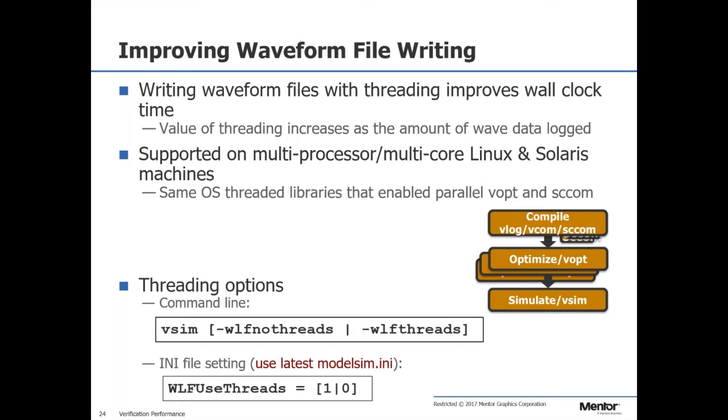So if you have a regression suite, you're better off running single tests in parallel. The only time multi-core is really useful is if you have one honkin' simulation that takes a week to run and you want to bring that down to a day or something. You might use a lot of simulation licenses to do that.